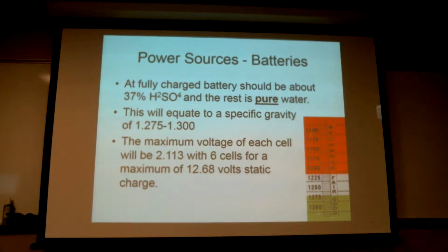Okay, with the lead acid battery, and by the way, a few of the numbers I'm going to give you, like voltages, will be, in this case, specific to lead acid batteries. When we get into some of the other technologies, you'll find those batteries operate at different voltages because we're talking about different metal electrolyte combinations. So for example, the lead acid absorbent glass mat, or AGMs, they tend to like to be about half a volt to a volt higher.